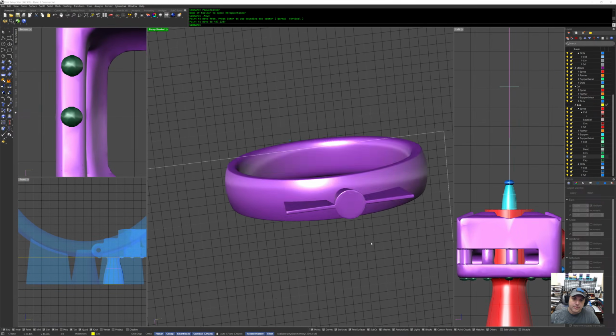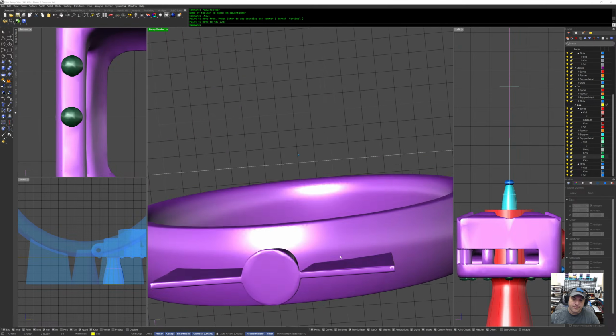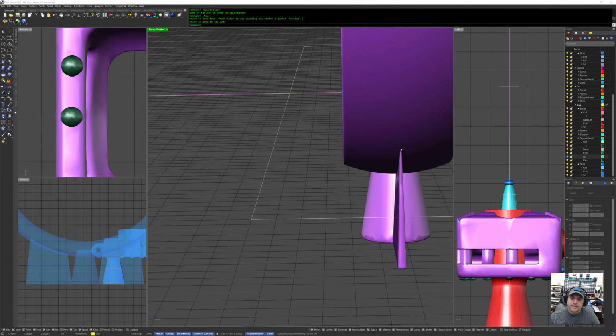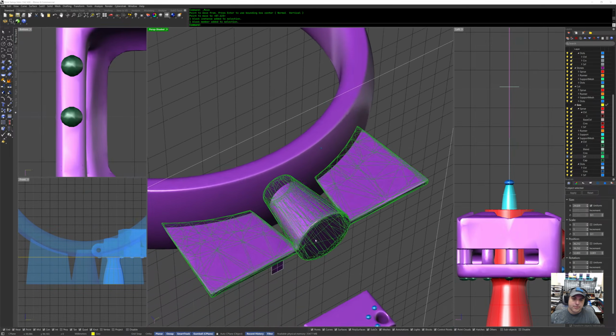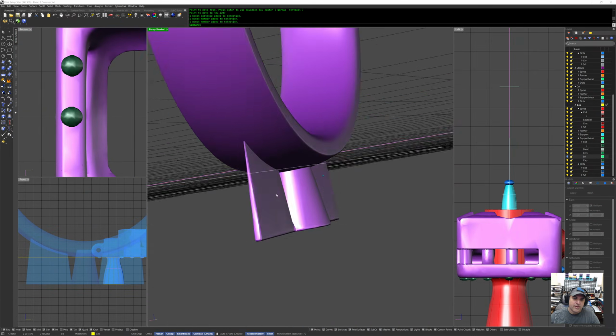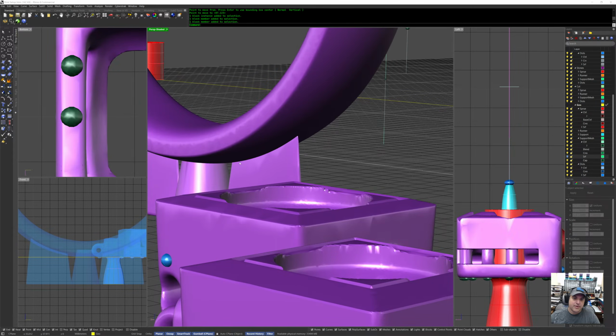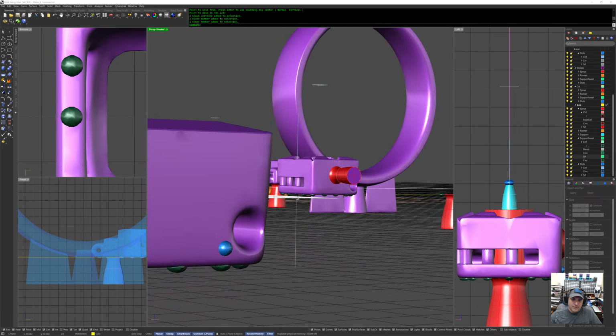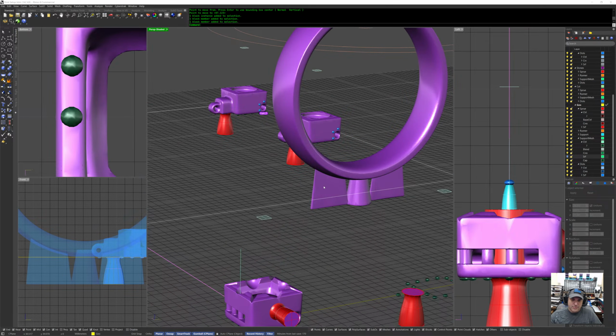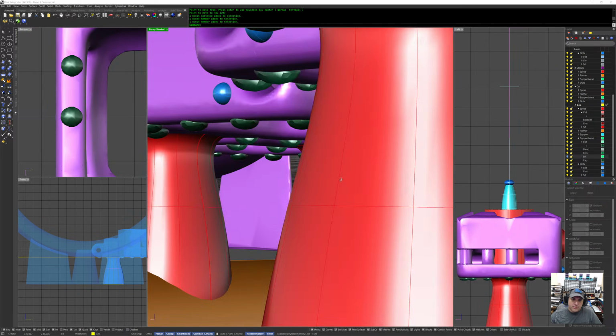This is how I like to do supports for rings. I have this fin, and the fin is narrow at the top. There's the sprue. And I like this because it's very easy just to run like the back of a razor blade against this edge. You just run not the sharp side, but like a dull-ish side, scrape, scrape, wiggle, and it breaks cleanly right there.